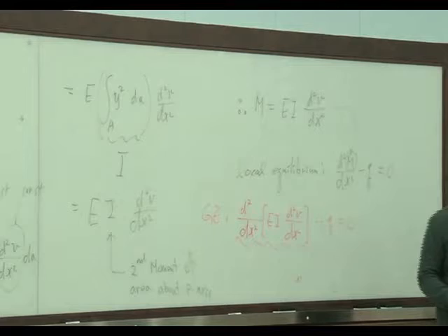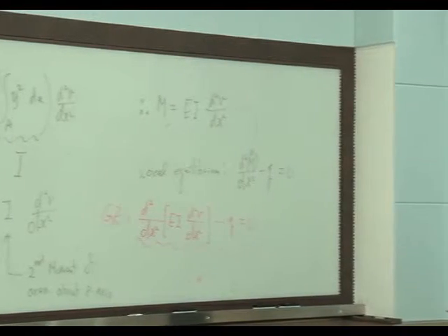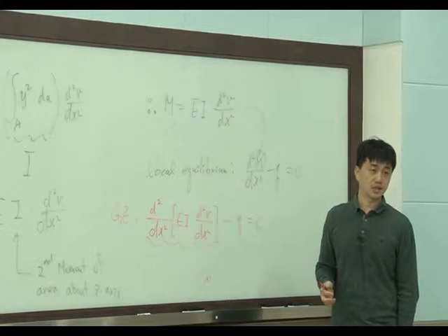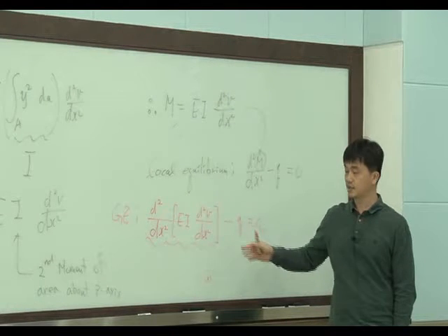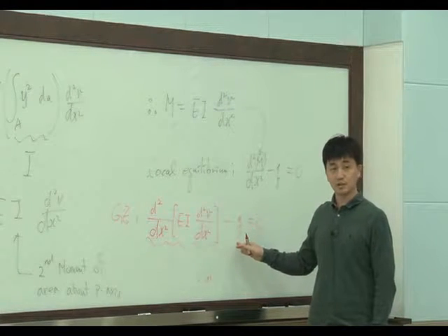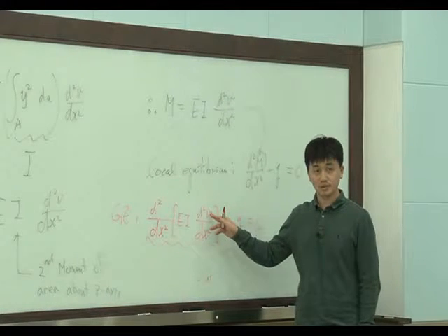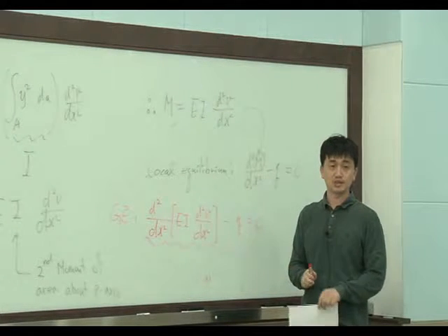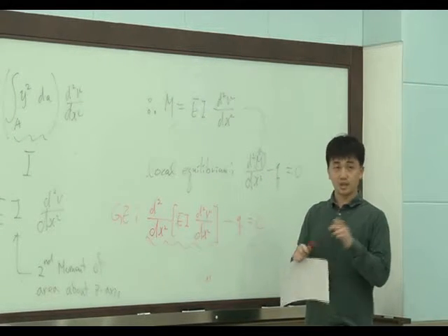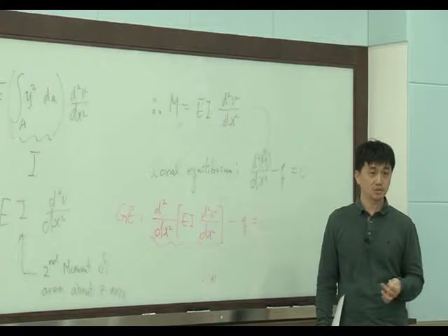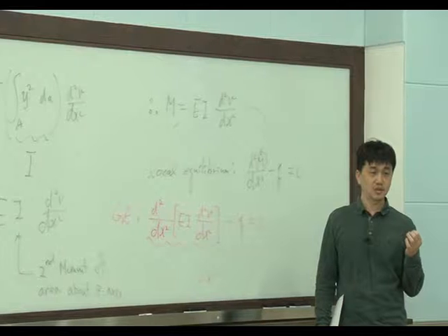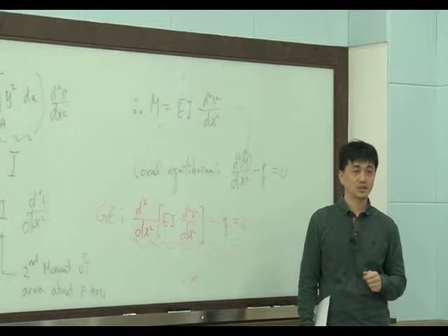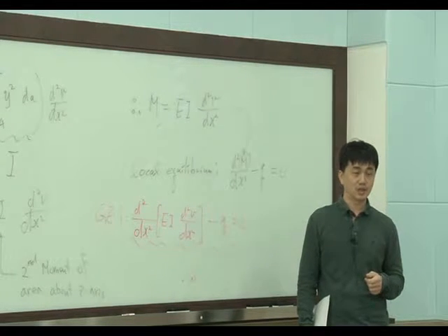So when we solve the beam problem, we need to use this equation. Okay, this is a fourth order ordinary differential equation, right? This equation gives us the relationship between external load q and displacement v, right? And to derive this equation, we use the local equilibrium equation, material law, and displacement-strain relationship. So we used all the basic solid mechanics, the governing equation, right?